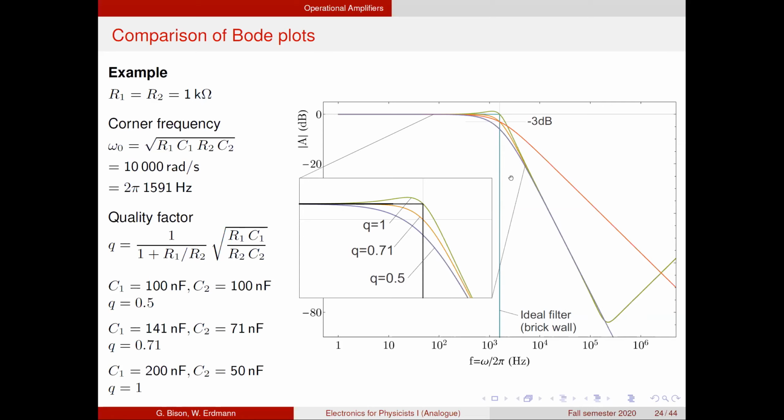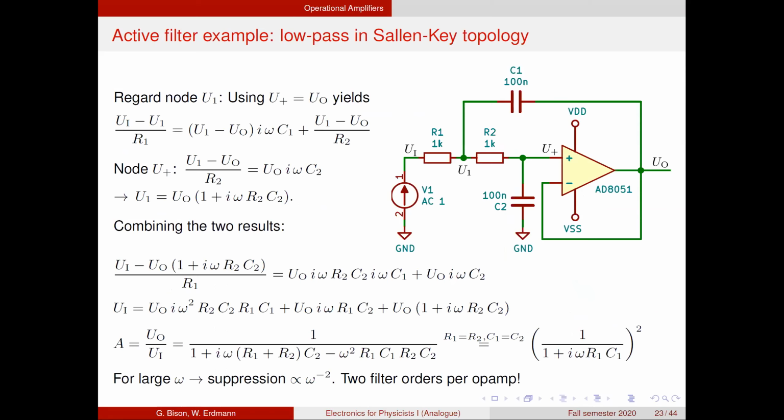And what you see here is that actually after it has suppressed the transfer a lot, it starts to go up again at really high frequencies, here at a megahertz. And the reason for that is this feedback capacitor here. You see, this feedback capacitor at really high frequencies becomes a short circuit.